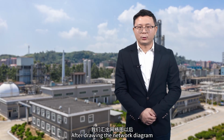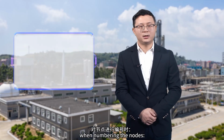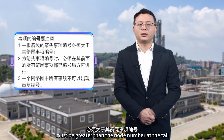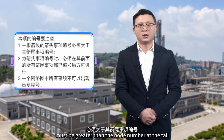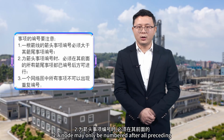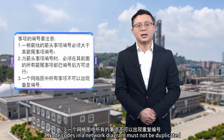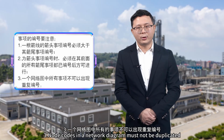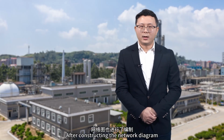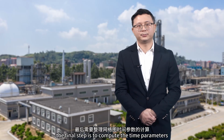After drawing the network diagram, the following points should also be noted when numbering the nodes. First, the node number at the arrowhead must be greater than the node number at the tail. Second, a node may only be numbered after all preceding nodes connected to its tail arrows have been numbered. Third, node codes in a network diagram must not be duplicated. After constructing the network diagram, the final step is to compute the time parameters.